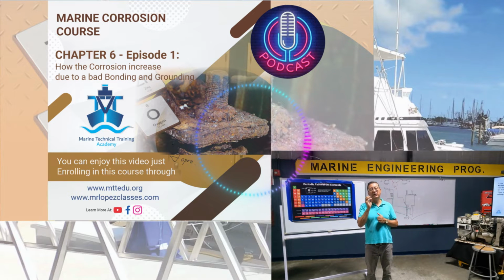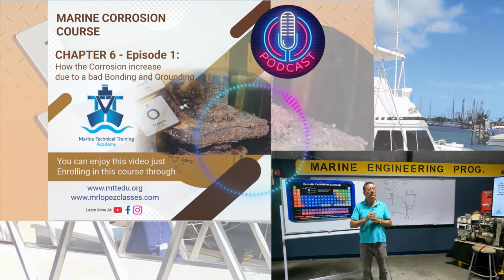If you have a loose connection on a battery, for example, you have batteries connected in series, 24 volts, and the cross cable of the series, the negative with the positive, that cross cable is loose, and this is the battery bank for the bow thruster. The moment that the captain activates the bow thruster, the batteries explode.